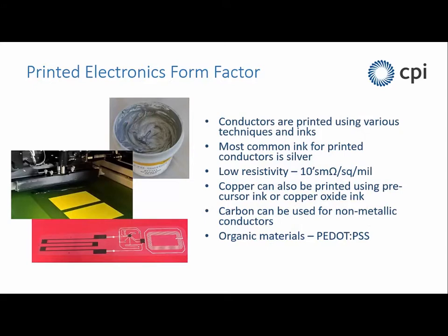So we've got a material that we can produce the circuit on. How do we produce it? Well, generally we make use of various forms of inks, and the most common ink I've already mentioned for conductor circuits is silver. So this will be a binder material that contains probably 70–80% of silver solids in some sort of flake form typically, and that is combined with appropriate materials to make an ink that can be printed with the right sort of rheology so that it will work well with, say, screen printing or with flexographic printing.